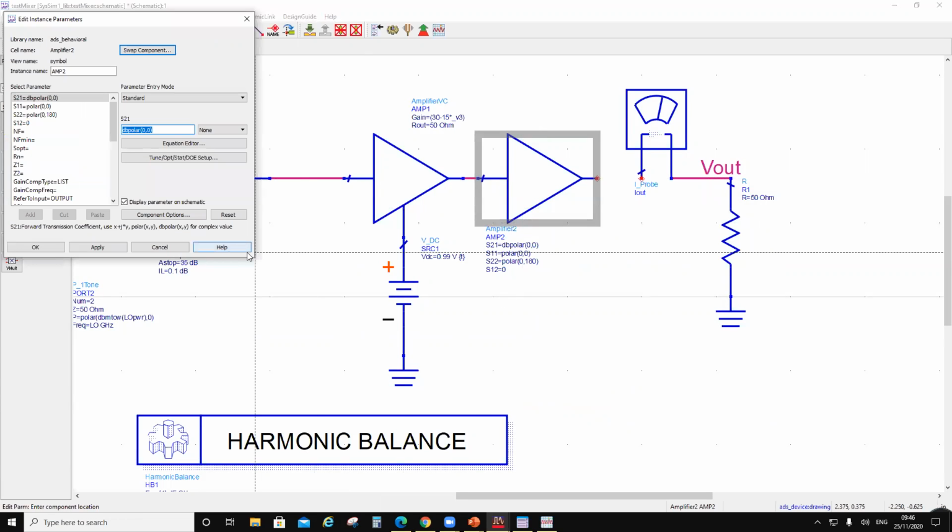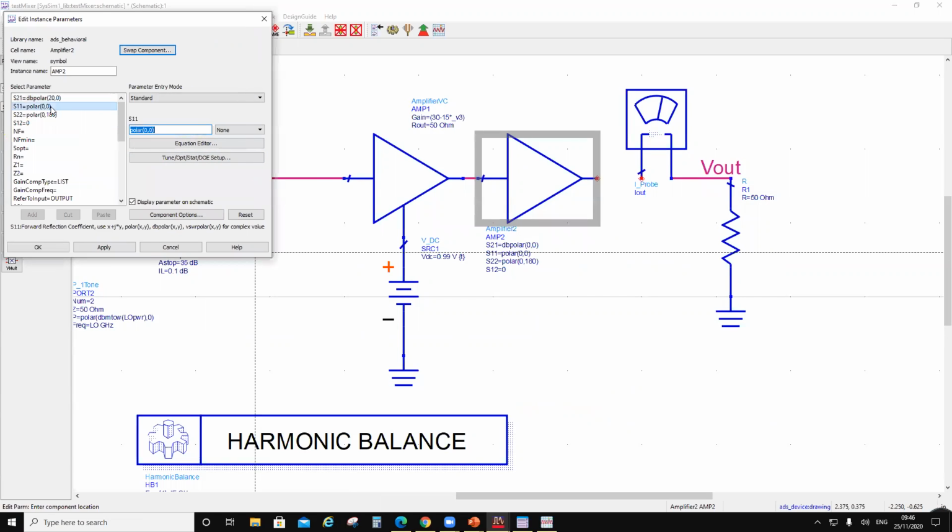Okay, so let's put this power amplifier. Again, gain I will put here 20. And over here I would put a return loss of minus 15 dB, minus 15, minus 15, and return loss again I would put a dB here. Much higher than the gain, so let's say 40. And noise figure, if you want to include noise figure, 8.